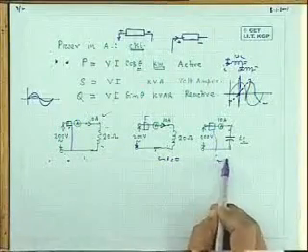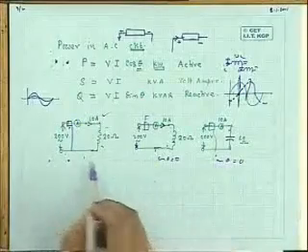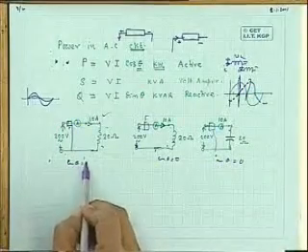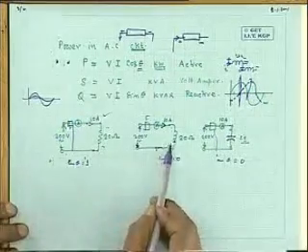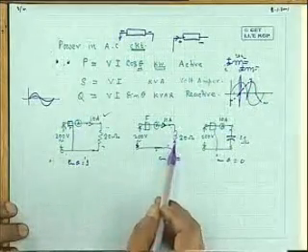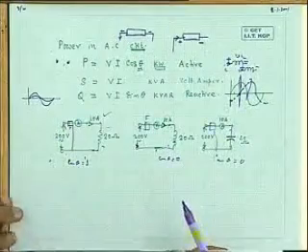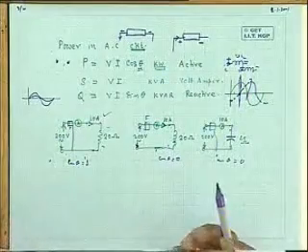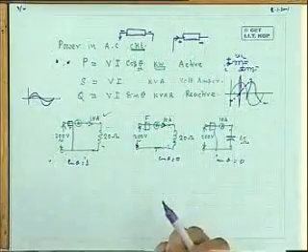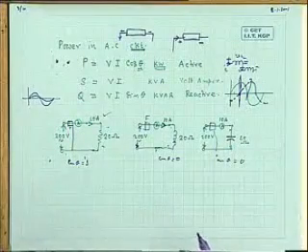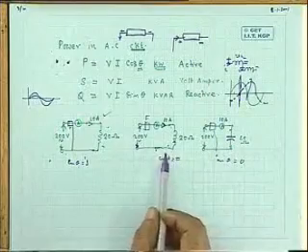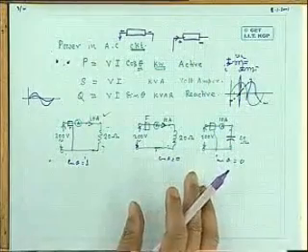Cosine theta, the power factor of this one here, is 0. The power factor of this one is also 0. But the power factor here is unity. Therefore, although they have connected an inductor, the consumer can always say, I have not used your energy at all. I have taken some time, but given it back in the next cycle, the next half cycle, and so on.